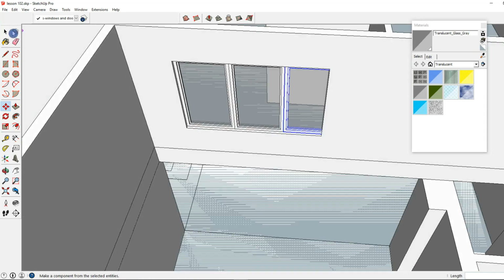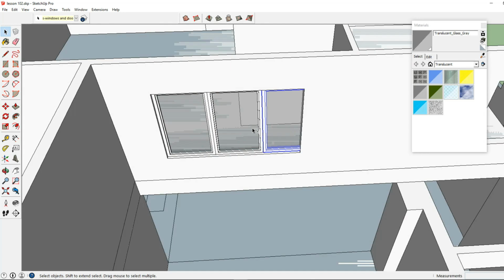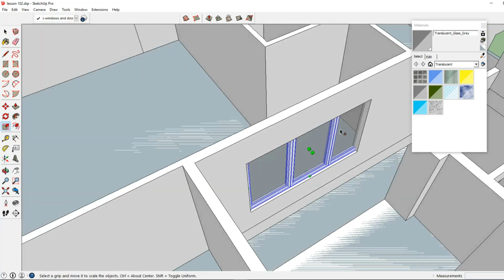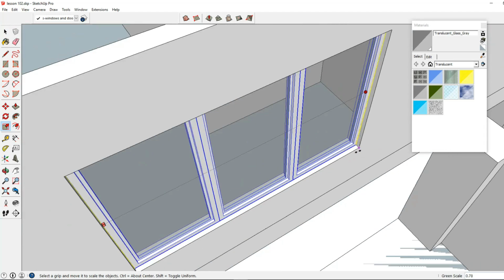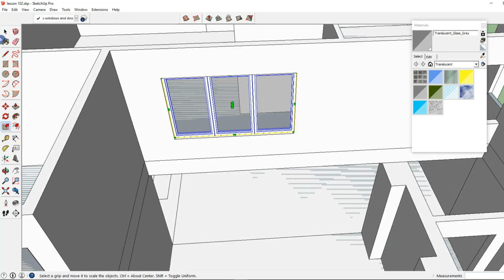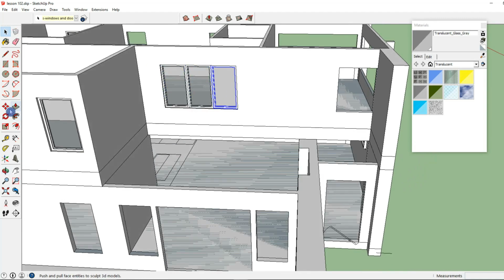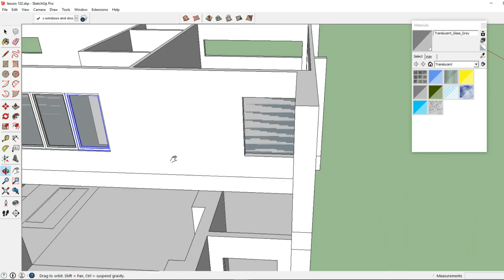And here we see that does not quite fit in that opening there. I could stretch that opening, or I could just grab all 3 of these windows, use my scale command, and find that middle point there, and I could just scale it and refer to this corner, and it will scale it right in that opening. So just a quick little trick to model quickly.